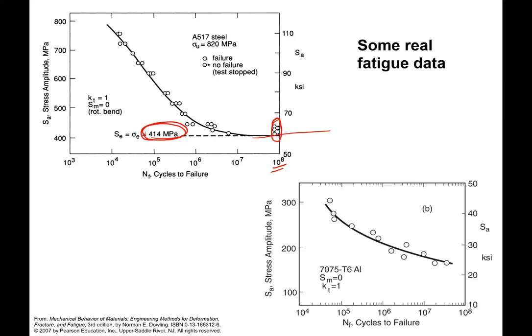All right, now I should be a little bit careful here, because in these tests there is a mean stress that's used, and it is going to be 0. That's what we've got here: sigma sub m, mean, equals 0. So that means that the maximum stress is equal to the negative of the minimum stress. So it's plus or minus, let's see, stress plus or minus 500 megapascals, for example, is the applied state.